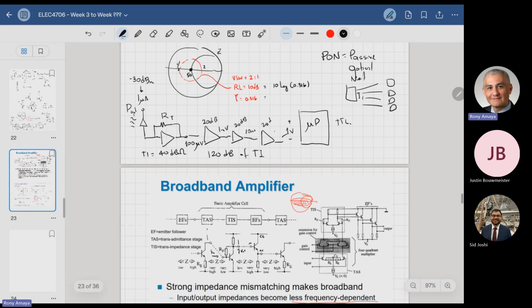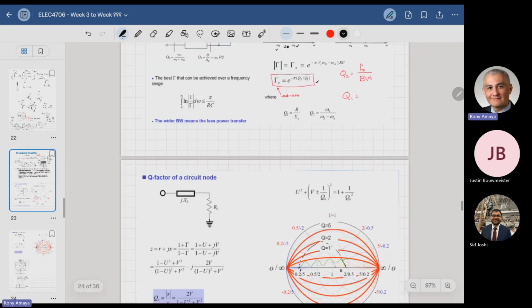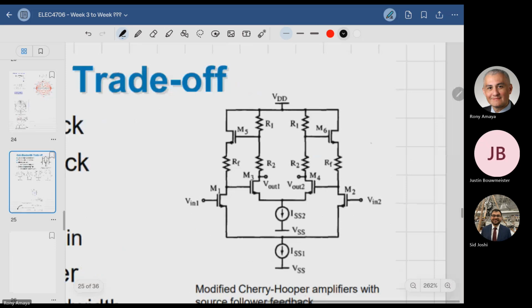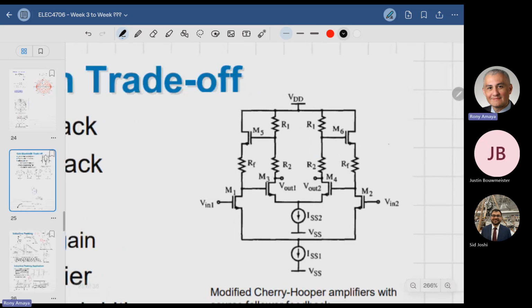What does that amplifier look like in the middle? Well, it probably looks something like this one. This is a voltage in, voltage out amplifier called a Cherry-Hooper amplifier. And we're not going to get into the transfer function, at least I hope not. But what it really does is that it effectively decouples bandwidth from gain. I can keep on increasing the gain without suffering the bandwidth. And anyone can see there. So I'm going to throw up there. Bandwidth is defined by what?